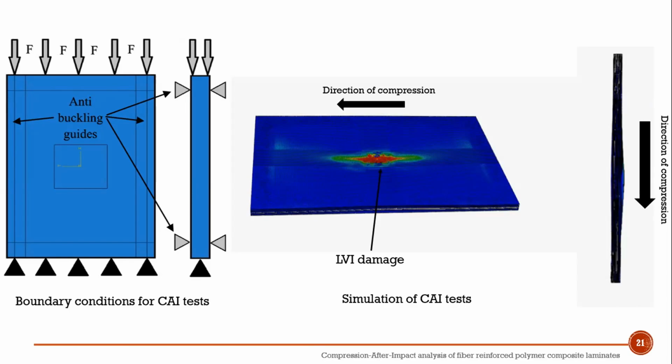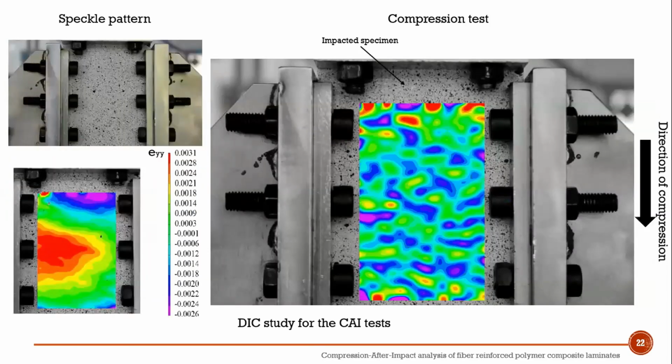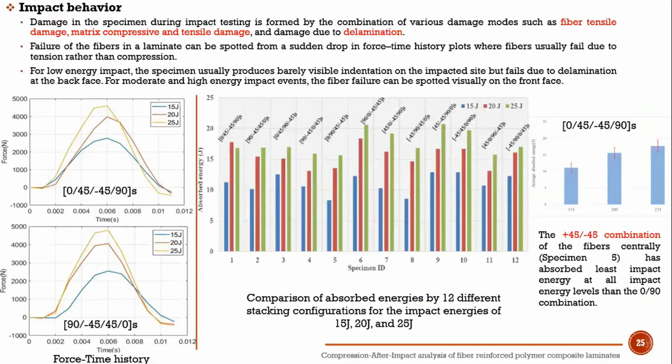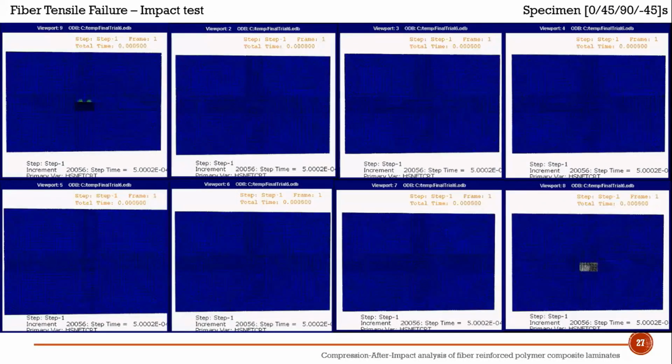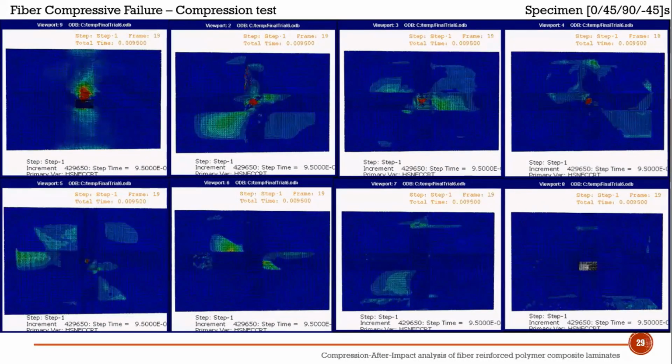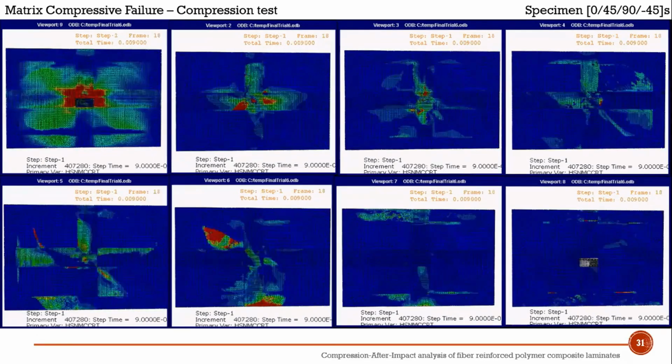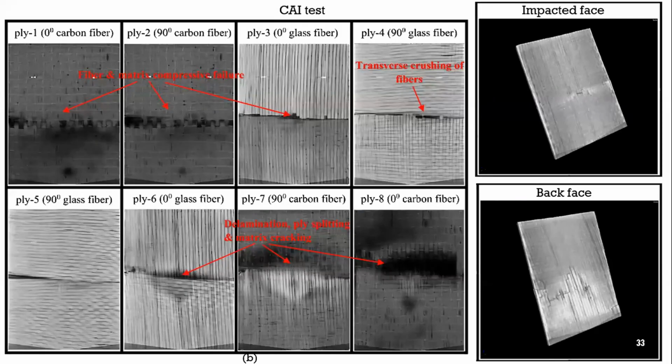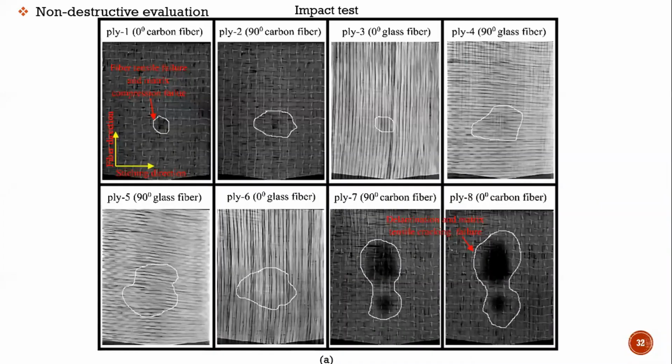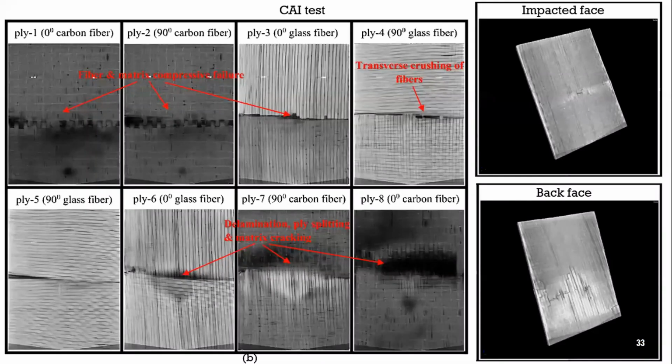Because my intention is to know the defects present if you're going for hand layup techniques, such as porosity or improper filling due to the resin curing time, etc. That's what I want to check, whether it's correlated with the premature failure. Here you can clearly see that delamination of the fiber is also shown. I think everything is covered.